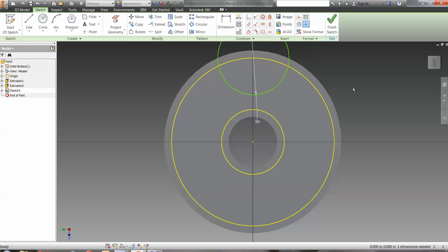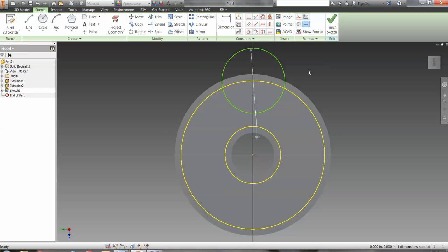That looks much better. Now what we don't have is we don't have this trimmed down. We want just this circle in here, not everything else out there. So let's go up here, and in our modify there's trim, little scissors, and we're going to come up and we're going to select the outside of our wheel circle, click that, and that disappears. That looks much better there.